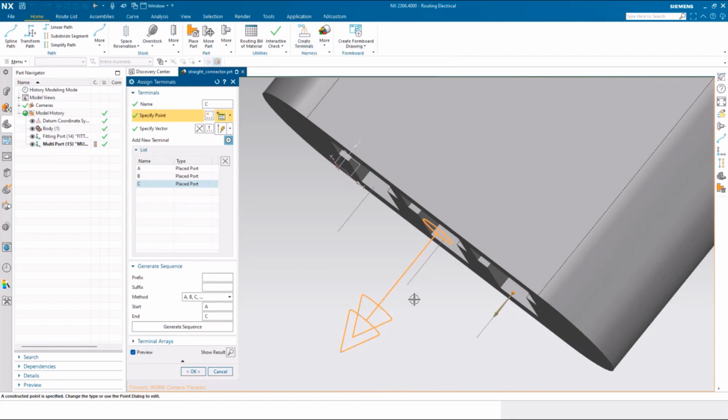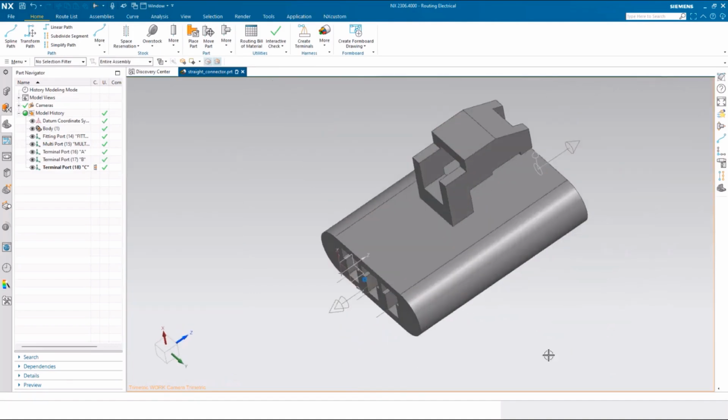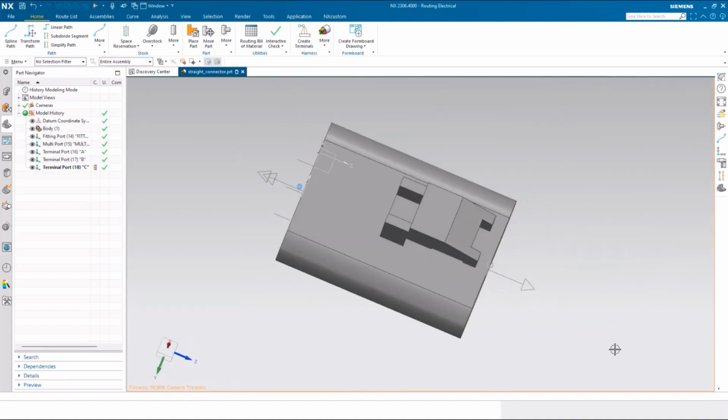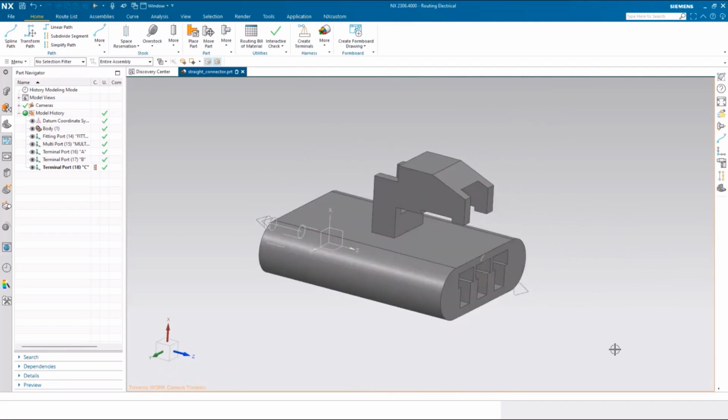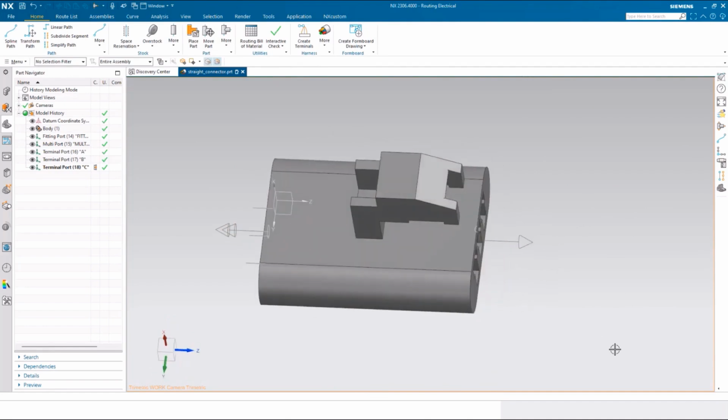So when the wire comes into this connector, it's your option if you want to actually model the terminals that show each wire coming into this connector. You can do that if you like. Again, it's optional. Let me click OK, and we're done. That's what the qualify process involves. Pretty much defining the attachment points for your part and defining where wires might come in.